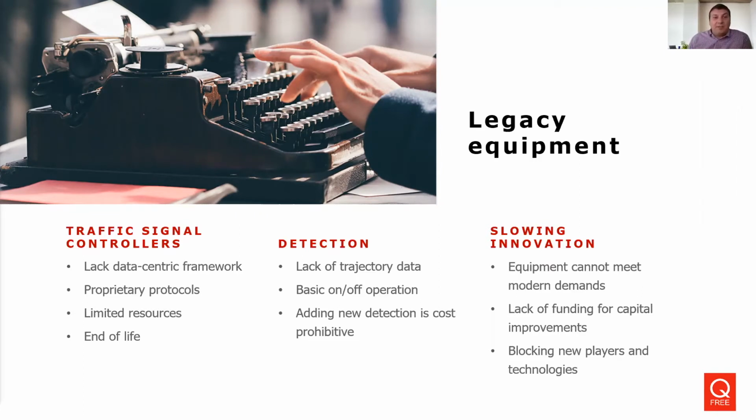And of course, end of life. I can't tell you how many controllers are out there in the field that are 20 plus years old. And I don't know if that surprises people or not, but again, there's no funding that's really earmarked directly just to upgrade a signal controller. It has to be through safety funding. It needs to be through environmental impact funding, things like that. So there's projects you can do it, but to some large cities, that funding is very hard to get or not available. So we have a lot of equipment out there that is operating 10 plus years past end of life. And it's really not fit for today's modern kind of operations strategies.